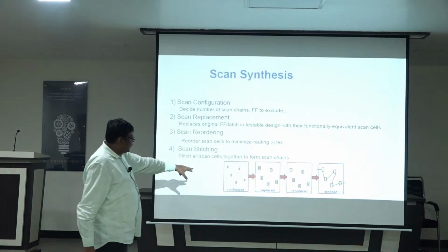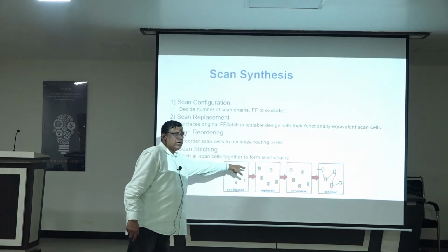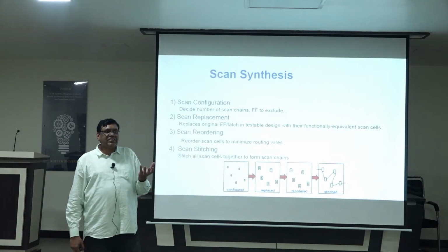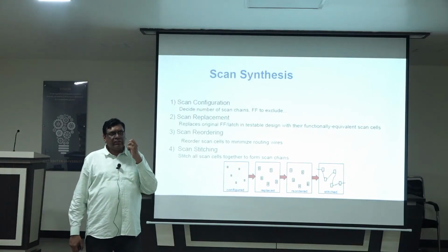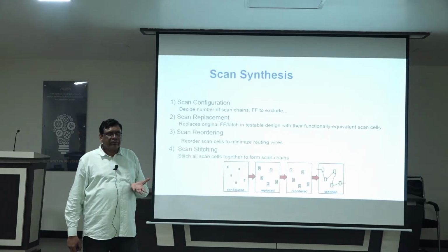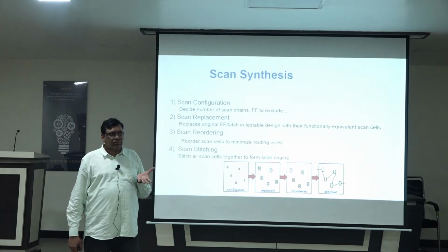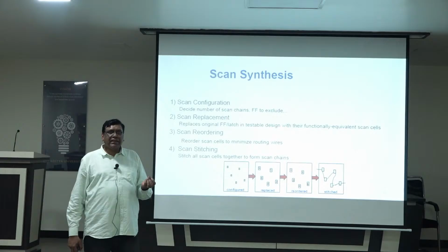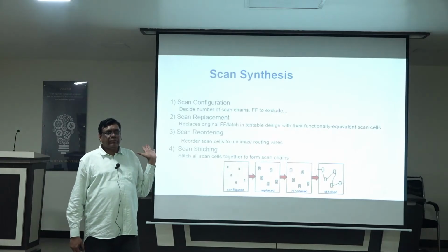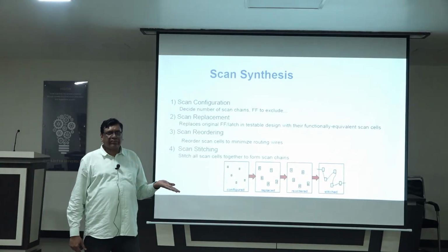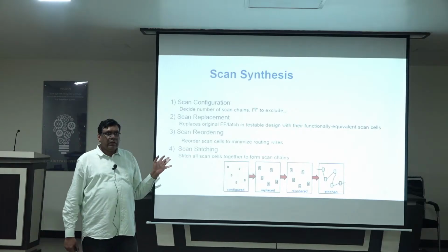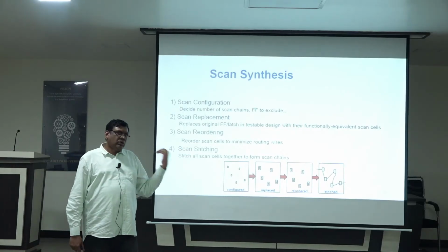That is the reason only a few are colored, and a few are left out. Some special-case flops will be there that the designer doesn't want to insert DFT scan onto. He doesn't want to test them either. If there is such a requirement, we have to leave them. They will tell us which flops we should not touch, so those flops we will not convert into the shift register. We will leave them. But we have another approach to cover that.